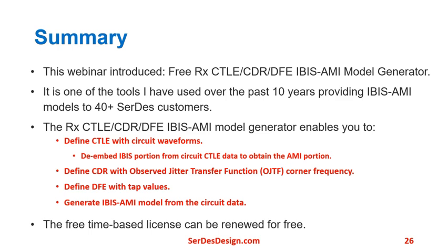The generator enables you to define the CTLE with circuit waveforms, define the CDR with its observed jitter transfer function, corner frequency, and define the DFE with tap values. It includes the ability to de-embed the IBIS portion from the CTLE circuit data to derive the AMI CTLE portion, and you generate an independent standalone IBIS-AMI model from the data.